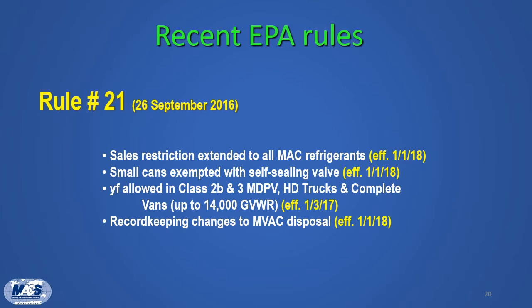So since that date, if you want to buy R134A, or if you want to buy any other mobile AC refrigerants, you have to have a MACS card or a Section 609 card in order to go into a parts store and buy refrigerants. Now, there is an exemption for those small cans that are sold at the big box stores, but the rule says that those small cans now have to have a self-sealing valve.